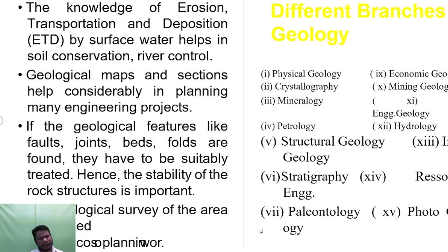Then the geological map and section help considerably in planning many engineering projects. If geological features like faults, joints, beds, folds are found, they have to be suitably treated. Hence, the stability of the rock structure is important. Pre-geological survey of the area concerned reduces the cost.